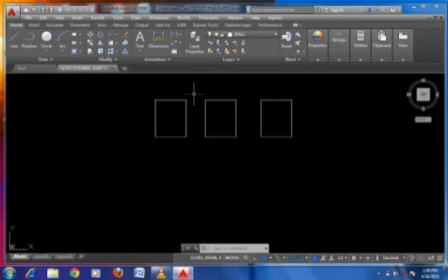Now I have modeled the external wall in 3 ways. I'm using my line tool, my polyline, and my rectangle tool. Once again, for the rectangle tool, it is art. And for you to press your art symbol on your keyboard, you press shift and you press 2. You now input your horizontal value first, you press comma and input your vertical axis value. So now we have to offset all these ones.